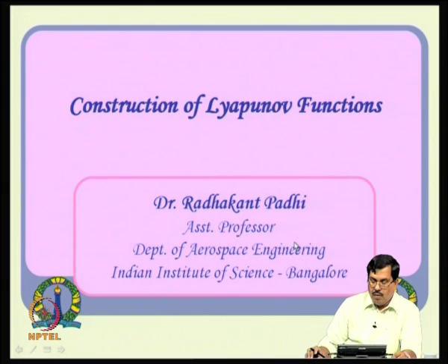And we also discussed last class some ideas for construction of Lyapunov functions, because of the standard Lyapunov functions, the quadratic functions, x transpose x or x transpose P times x, where P is positive definite. That is a very standard way of starting a guess. If it does not work, the alternative idea is to select a total energy, kinetic energy plus potential energy, but other than these two we are kind of blind about what to take.